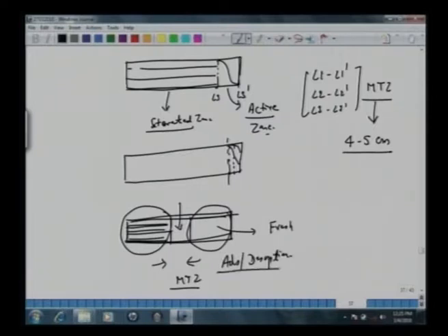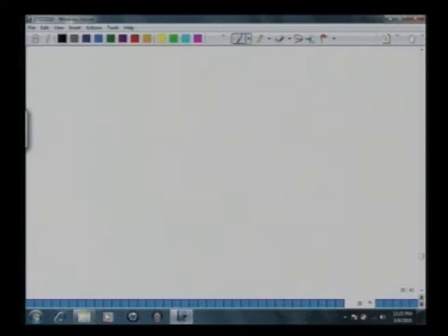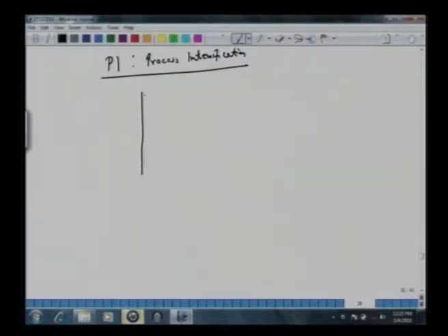All right, and this argument also brings us to another very important thing, which is PI, or process intensification. Without getting too much into the details of process intensification, we are trying to say here that since we realize that at any time the mass transfer zone is very small, so let's say in a vertical column we have this zone which is the MTZ.